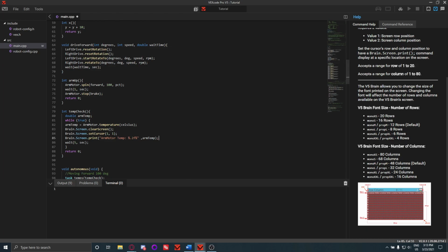This happens at around 55 degrees. So it's always a good idea, if they're getting close to that number or if they're above it already, to turn off the bot and cool it down before you start testing stuff, because it will skew your results.